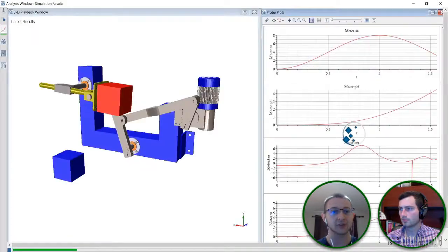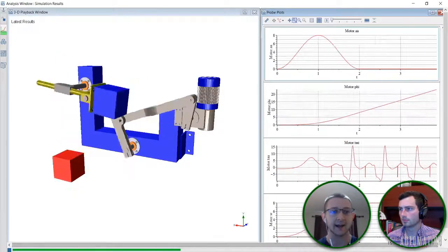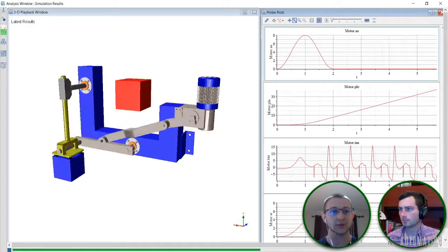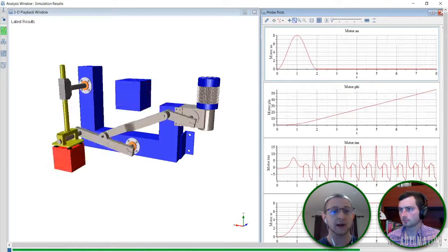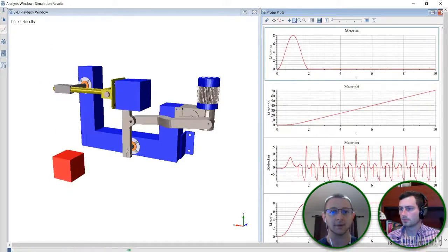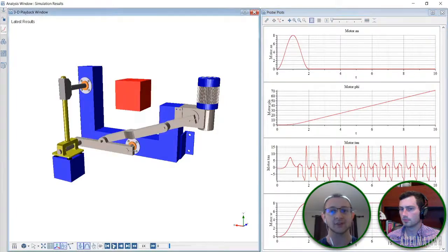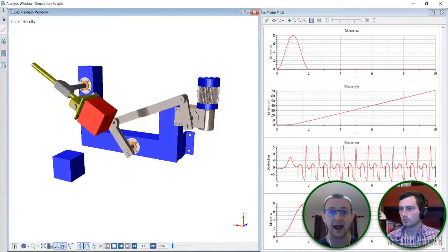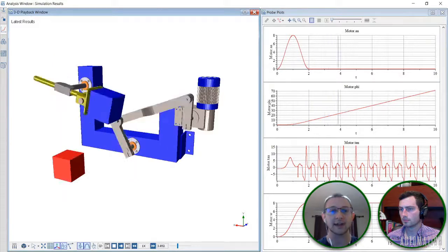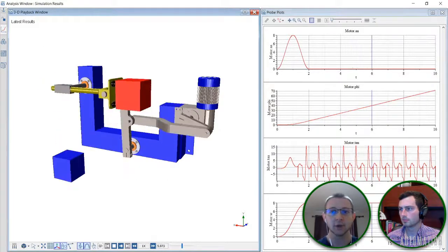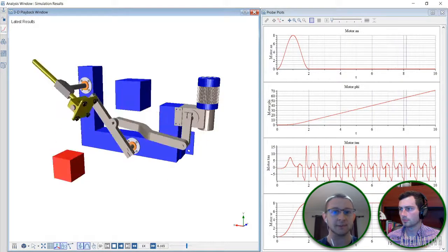And what's going to happen in this simulation is, because I brought in a CAD, I'm going to get all those mass and inertia that we were talking about earlier, automatically calculated, automatically connected together. So when I get this simulation, I'm getting something that's very accurate, and it's not lacking any of those dynamic effects. So on the left, we can see this 3D playback.